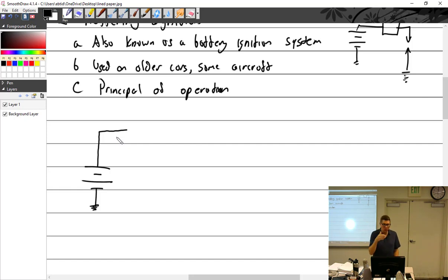But one of the choices I had now is electronic ignitions. There is a supplemental type certificate, which means the FAA will allow you to do it, because the type certificate for my airplane and engine says that's the magneto you will have. But somebody's making these electronic ones now, with no moving parts. It's all electronic. You just put it on the back, and it has a part that spins just like a magneto, just so it can sense where things are.